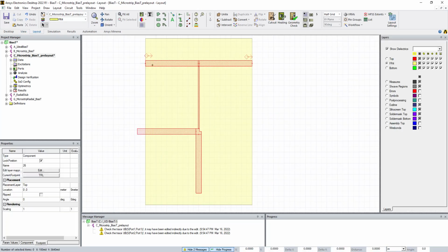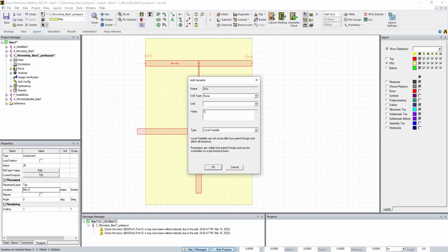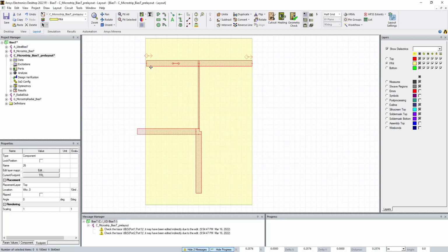So what we want to do is this first one, let's not start it at 0, 0. Let's actually start it at this offset. So I uncheck the block, and then we're going to say, hey, don't start at 0, 0. Start it at W trace offset, comma 0. So we're going to start that left thing over here, and again, we're going to make this trace offset just 10 mil. It could be 10 mil, 20 mil, doesn't matter. Okay, so I just scooted that over.